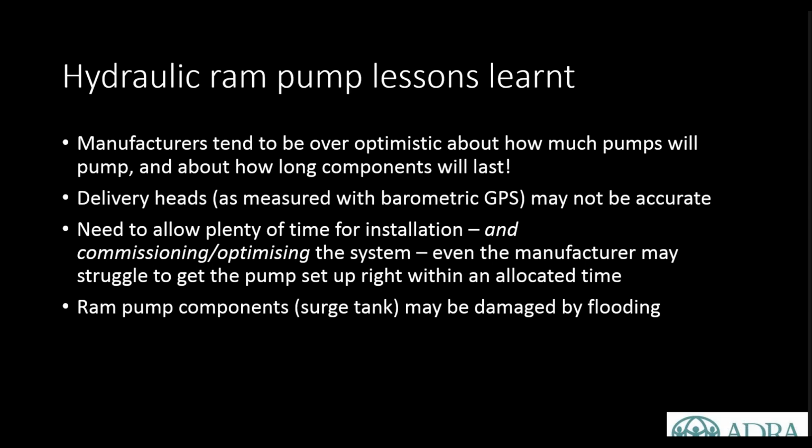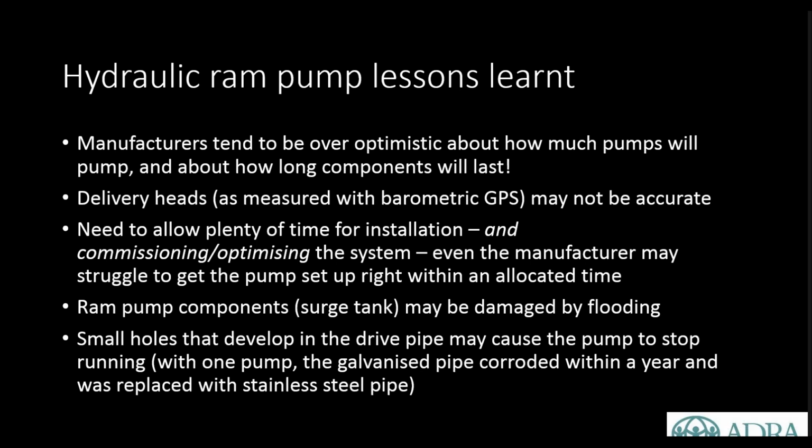And I mentioned before that the ram pump components, such as the surge tank, can be damaged by flooding. We've also had small holes develop in the drive pipe. We had one galvanised drive pipe where a tiny hole developed, which meant that air leaked into the system, and once we got air into the system the pump wouldn't run.